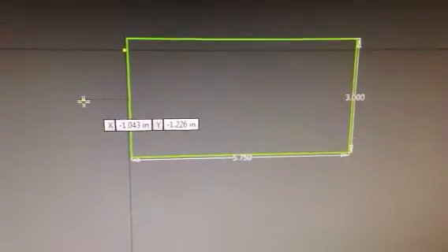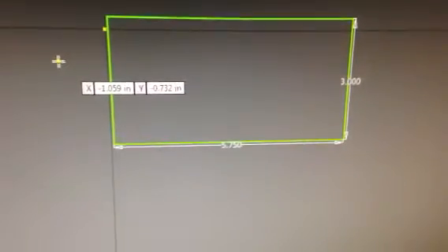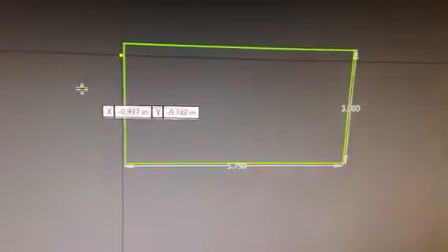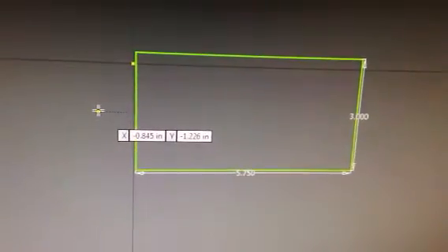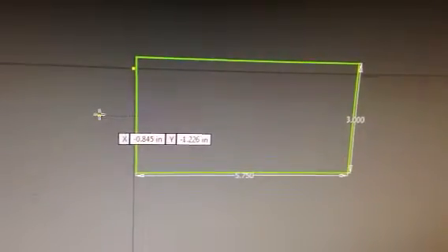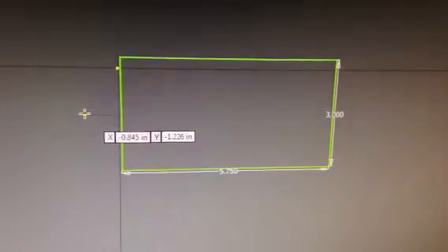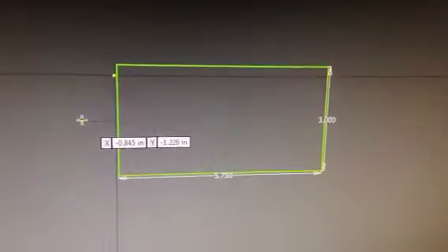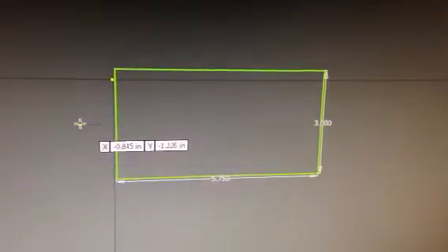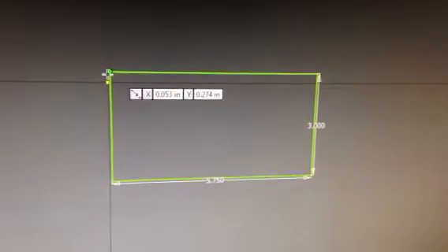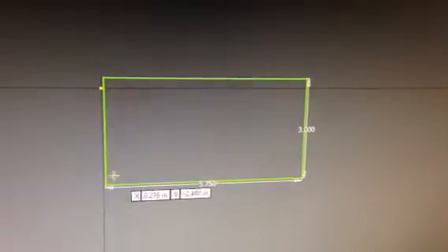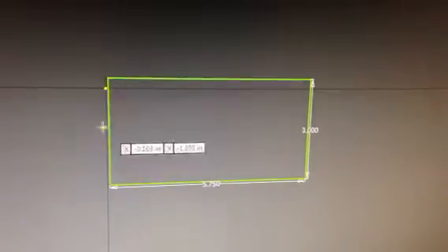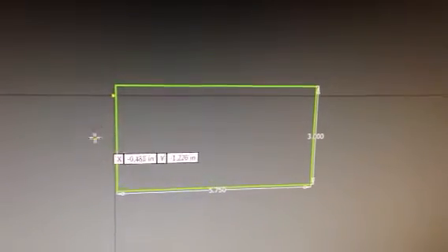Now do you see how, yeah, there you can see those little dotted lines? If I move up, they go away, right? But if I come back down, oh look, they're there. Those cool little dotted lines actually tell us that we are exactly halfway. Okay, we are 1.5 inches from this up here, and we are 1.5 inches from this edge down here, right there.